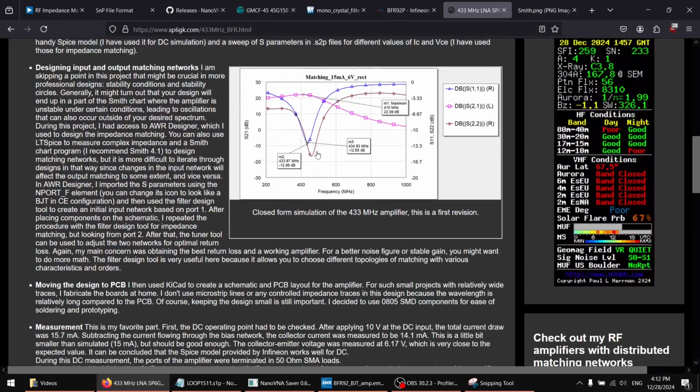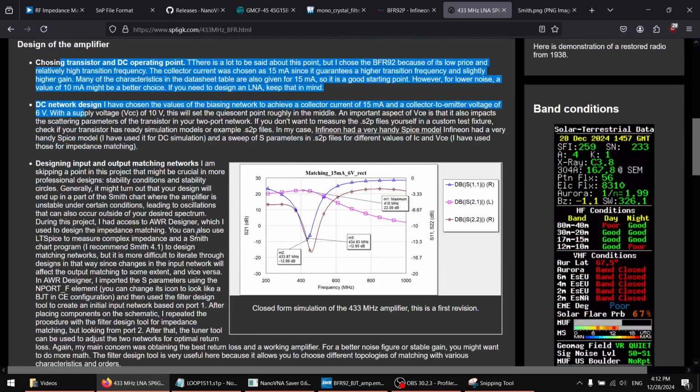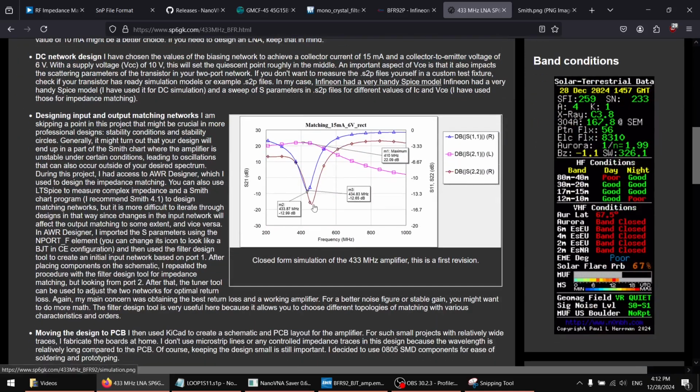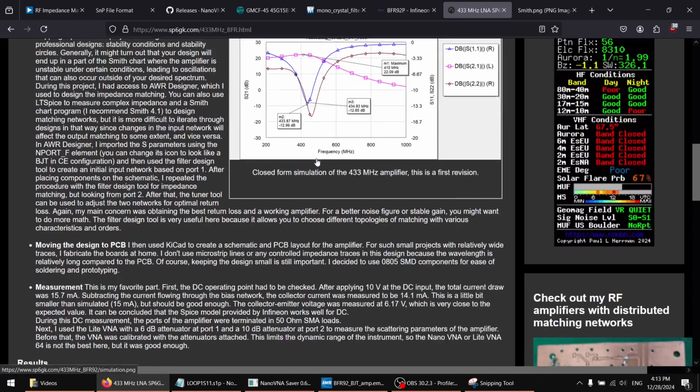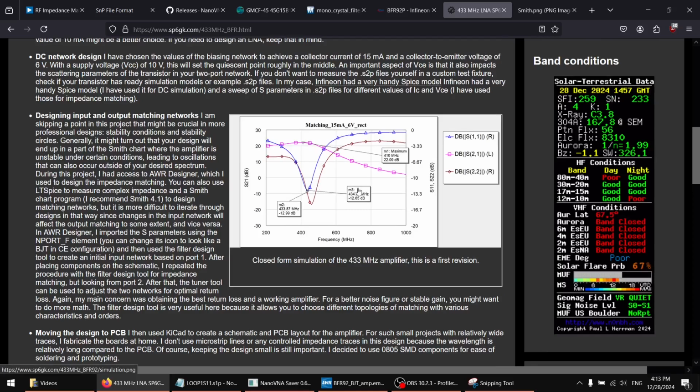harmonics, for example. So you can see that this amplifier will actually work quite poorly for the harmonics of this 433 megahertz signal. So for example, for amplification of an intermediate frequency, or a local oscillator that is constant in frequency, this is actually a pretty nice choice. Of course, it requires a lot of time to design this, but as an engineer, you have the freedom of choosing the gain, the noise, and the bandwidth of your amplifier, instead of relying on a ready solution that may not be possible to accommodate to all those parameters.